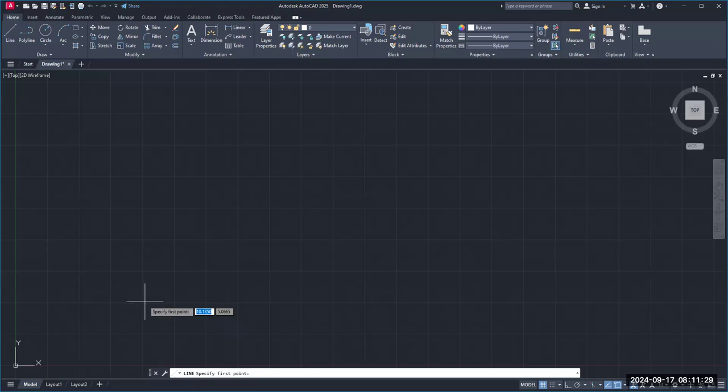All right. I've anchored my line, it's kind of going different angles and so forth. I don't want to do that. So what am I going to do? I'm going to hit F8. All right. So now we have a line anchored. It's anchored and it's moving perfectly horizontal. So you see the angle is not really changing, but the dimension's still changing. And we're going to make this first dimension, if you're with me, we're going to make it 2. And then we're going to enter.